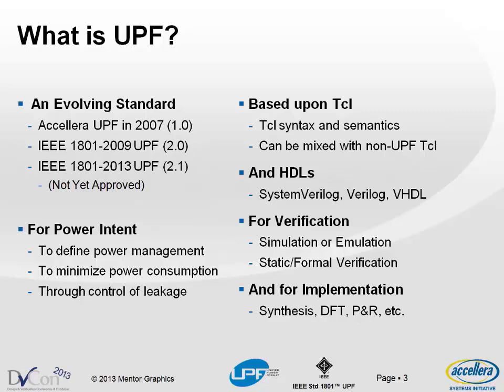It's a standard for modeling power intent, to define power management with the main goal of building in the structures necessary to minimize power consumption, and in particular through control of leakage. It's based on Tcl, so it uses Tcl syntax and semantics. You can mix it with non-UPF Tcl, so you can write scripts based on Tcl that include UPF commands.